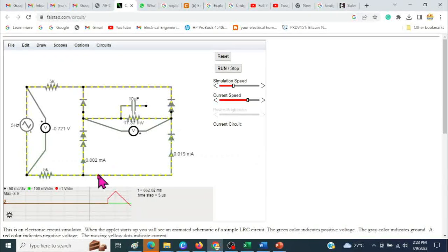You can see this current has now started flowing, and this is the path. And you can see this current is increasing gradually, 0.3135. This is minimal, where a leakage current we can say is 0.003 milliampere. So we can safely say that these and this are not conducting, only this path is conducting.